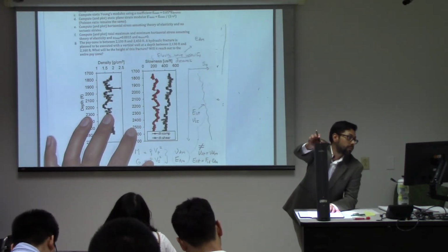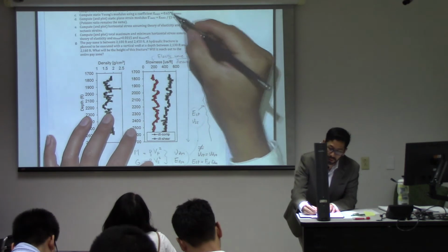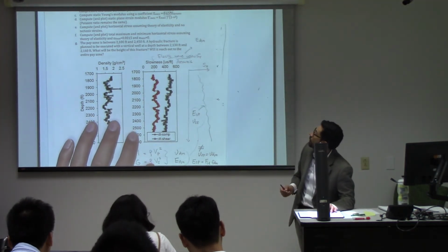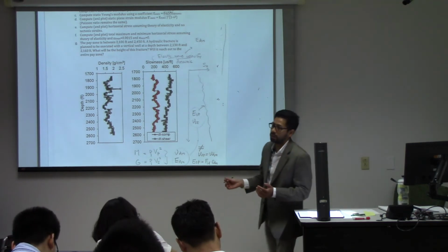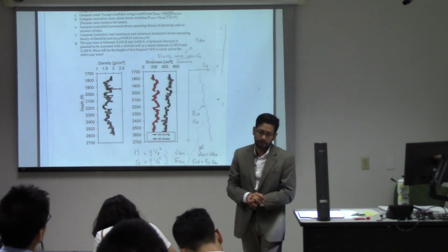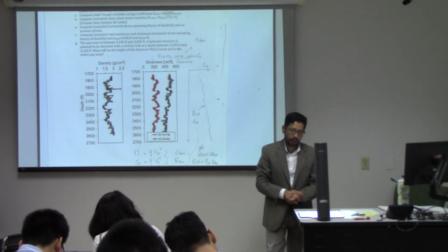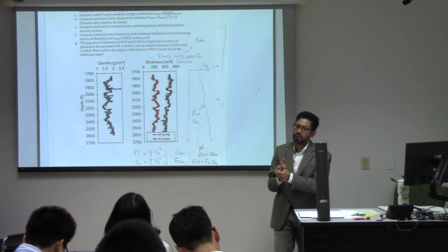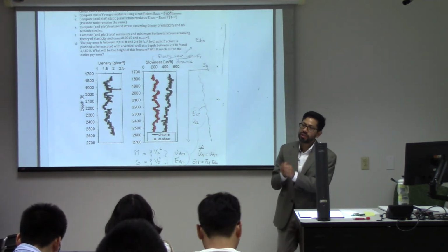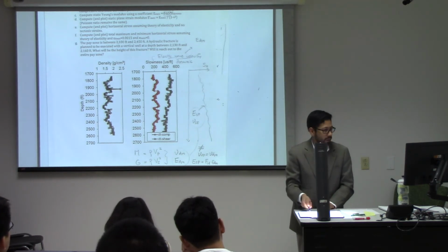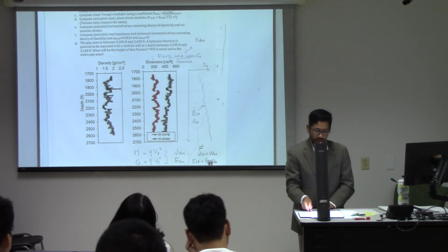And for this example, you have it over here, right? 0.65. Usually the static modulus is smaller than the dynamic modulus. And that's linked to the magnitude of the strain and also to the strain rate. Those two things are going to determine what this coefficient is.